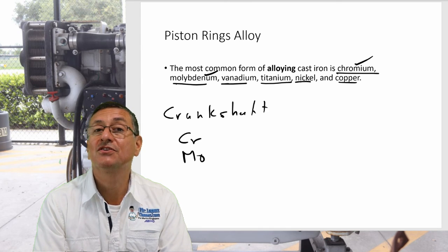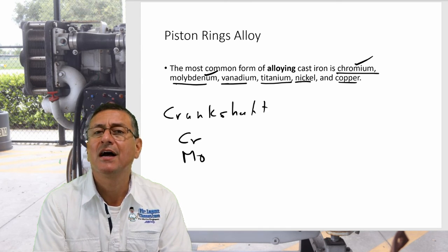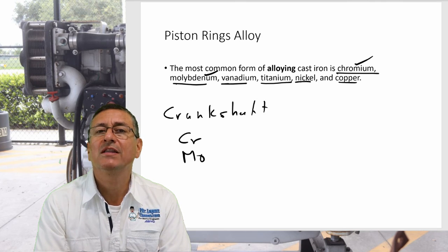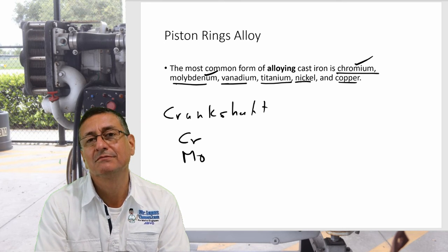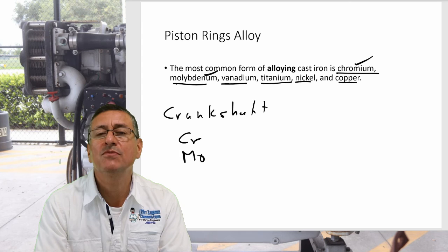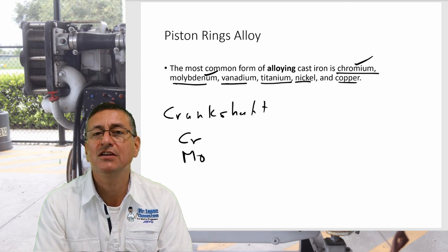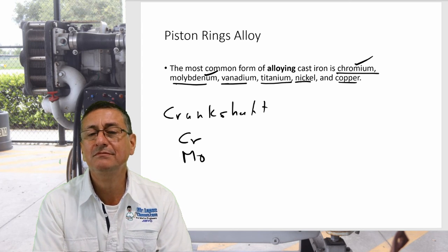Probably the problem is on the piston rings. And what is the consequence? I have low compression. What is the symptom when the compression of a diesel engine is too low?